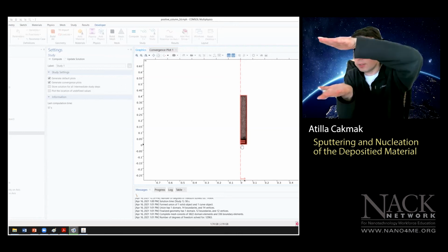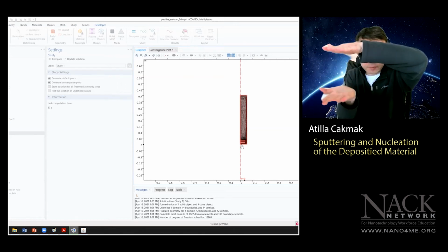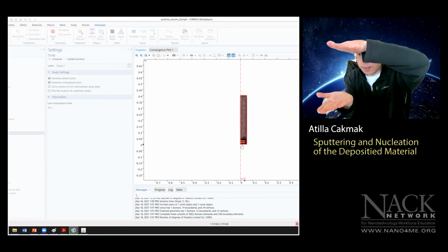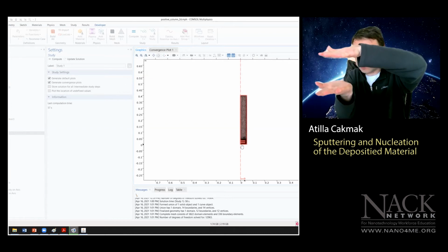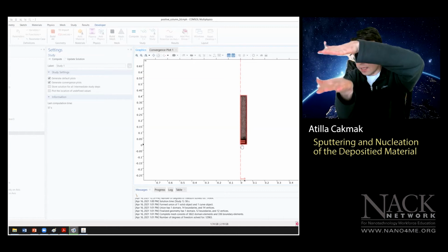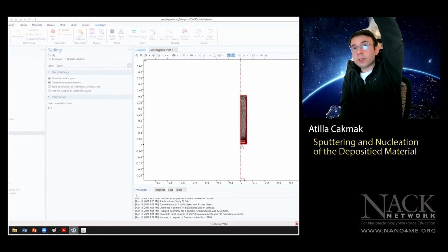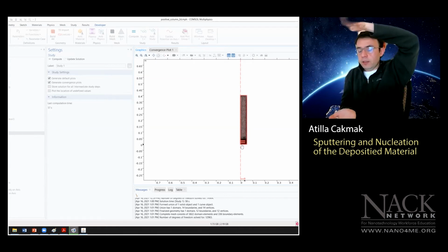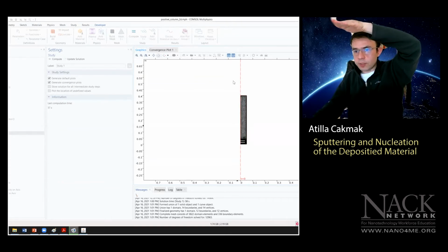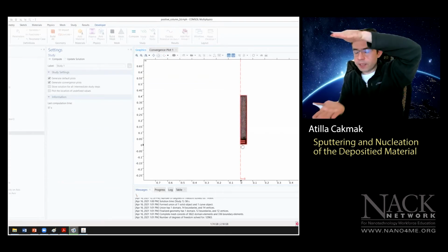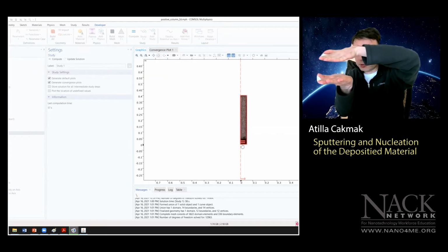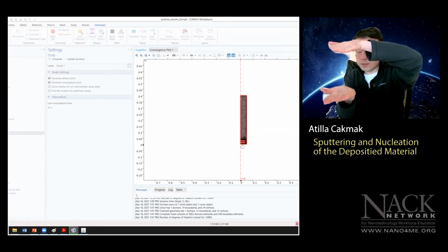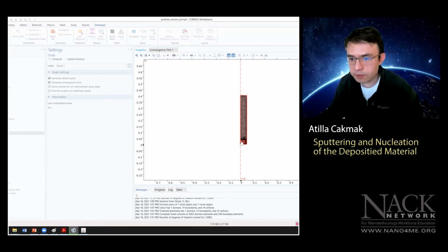This is kind of equivalent to saying, if I put them closer, I might increase the electric field between these two plates. Because they were far away from each other, the influence of the electric field was weaker. If I make them closer, the voltage drop will be drastically higher across these two electrodes, so I might give enough energy to ignite the plasma. I think this will still not be enough, but I have to be careful.